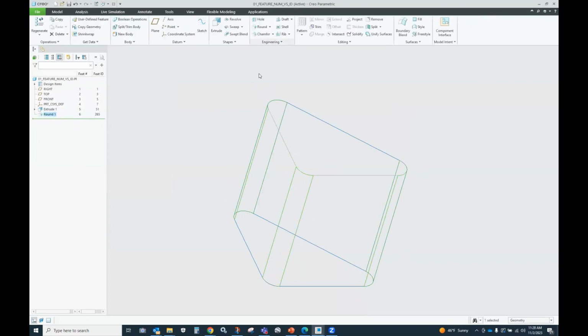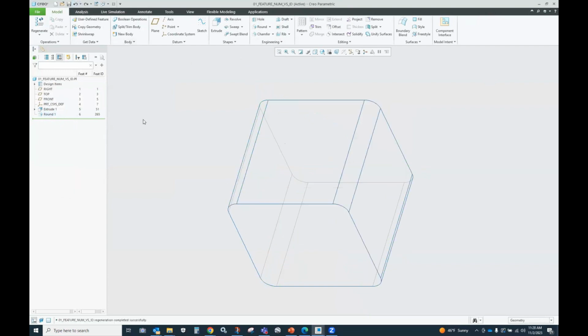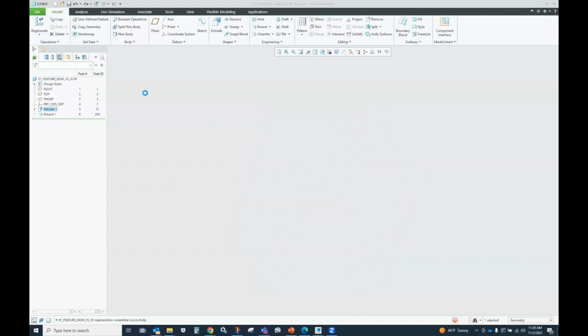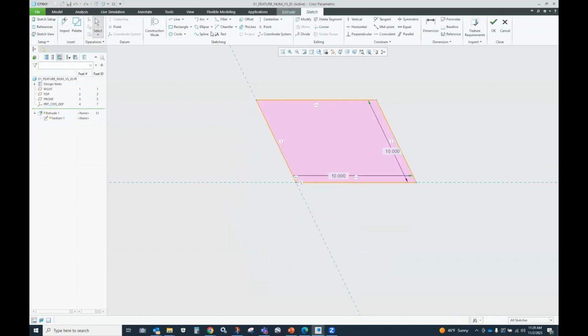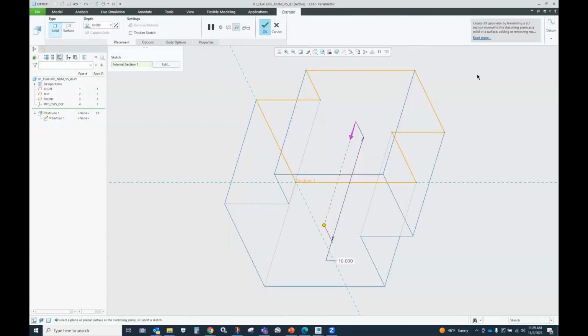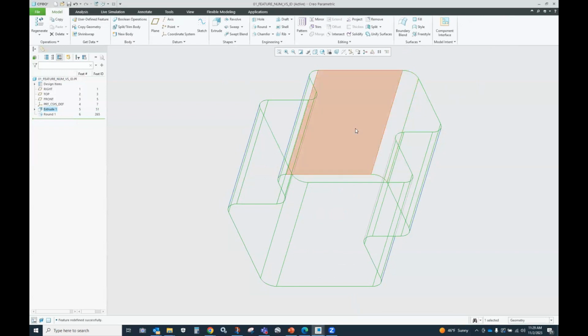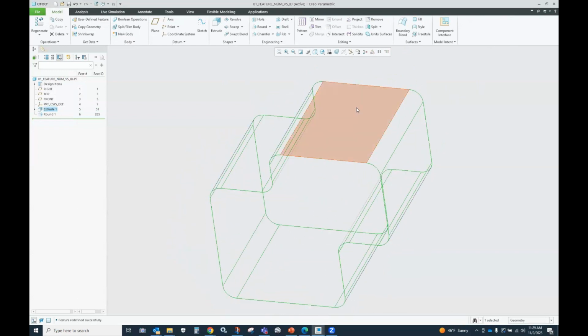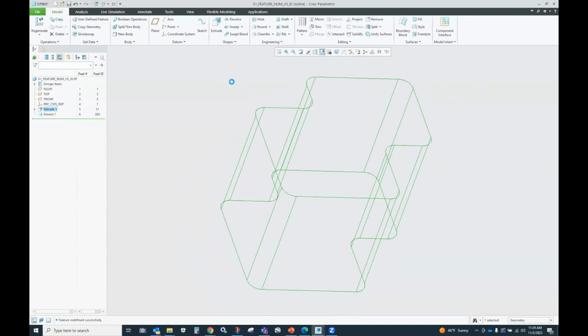Okay, so the nice thing about that is I can add geometry to this as well, and my round won't fail. If I take that and I go into my sketch and I add geometry, right, and then I delete the pieces I don't want, my round still gets created. Now I got more edges getting the round. But again, because all those edges are part of that intent selection.